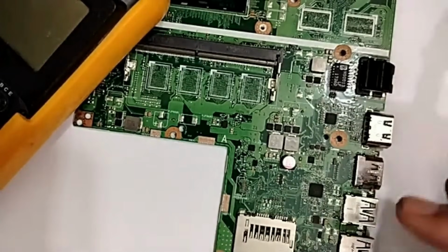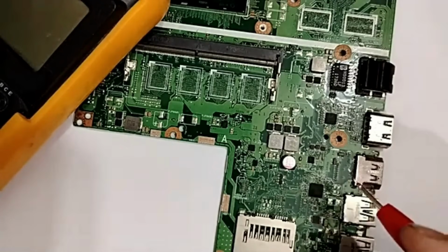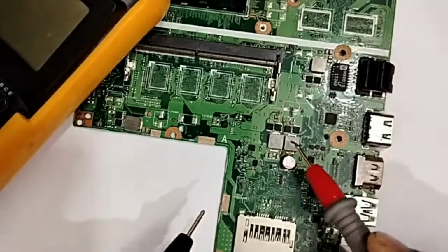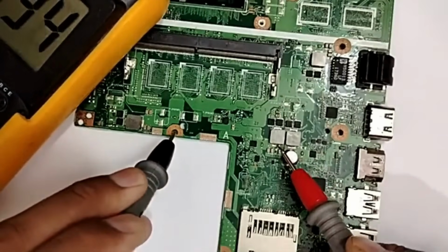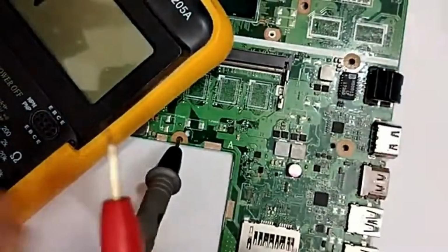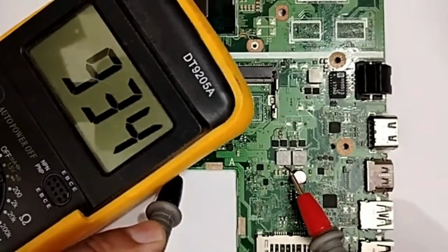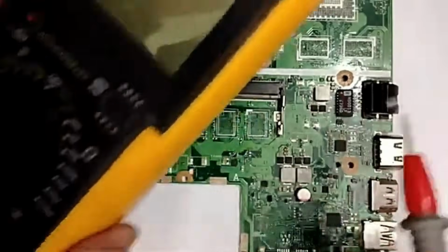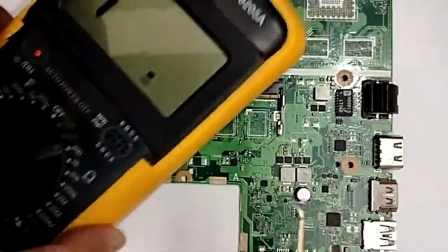But as I told you before, here we make things easy. We follow the process and we follow the logic. We don't do things randomly. So as I told you guys, always locate the inductors. The inductors are always connected to the power rail. That's why we have a high reading here, even if we check in ohm mode, the same.